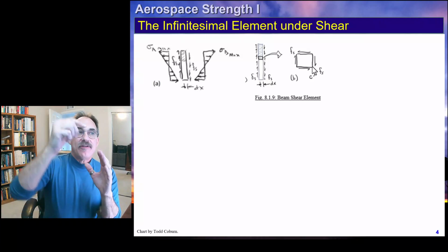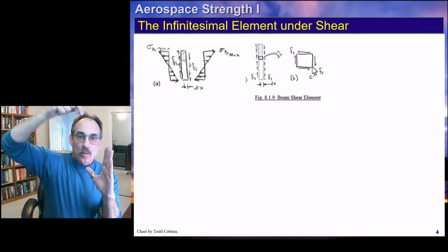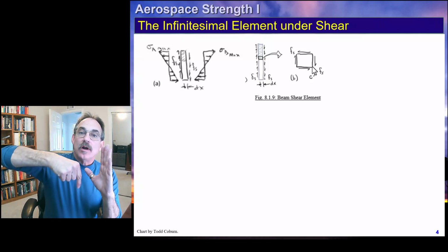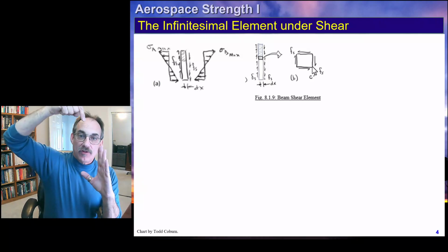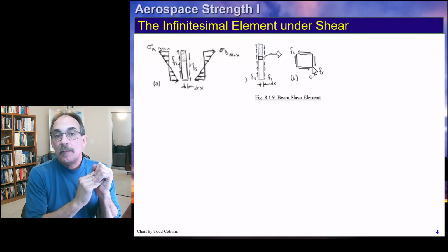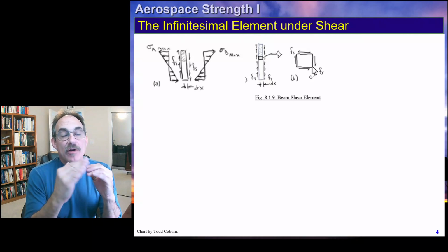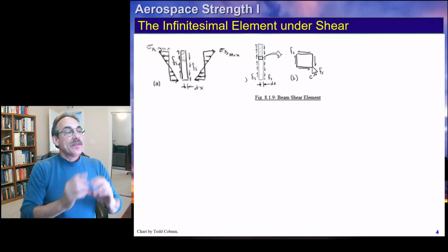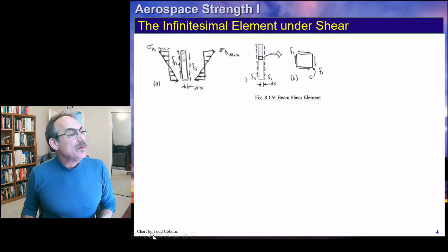However, on the right face, we have a shear force acting downward, which means we have a shear flow acting downward, but the shear stress and the shear flow are growing as you move downward because we have more and more Q. Remember, we're calculating the first moment of the area of everything above. Remember how, on our little cross section here, we focused on this upper face right here, only part of the face from there to there and from here to here. That's going to give us the shear flow right underneath here.